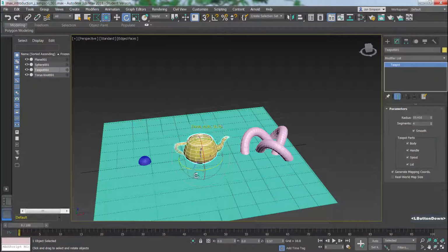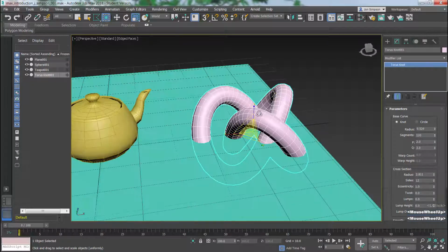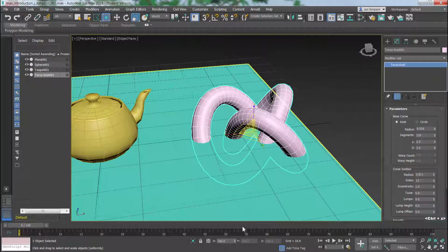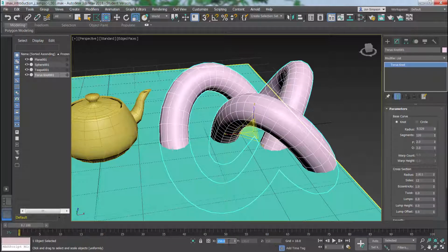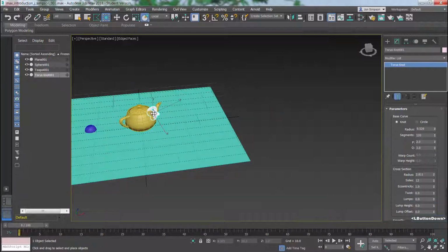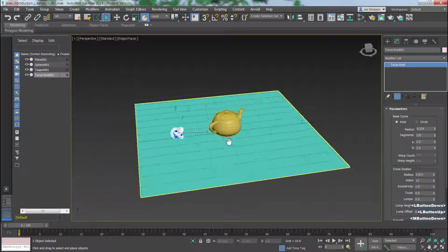The Rotation tool has a different widget but is basically the same. Click the solid line to rotate the object on that axis. With this tool, the numbers below the time slider now represent the object's rotation in 3D space. The Scale tool has a different widget, but again is basically the same. Click the solid line to scale the object on that axis. With this tool, the number below the time slider now represents the object's scale in 3D space. Always try to scale the object uniformly, as non-uniform scaling can cause problems when animating an object. The Select and Place tool lets me move and orient an object to any face in the scene interactively.